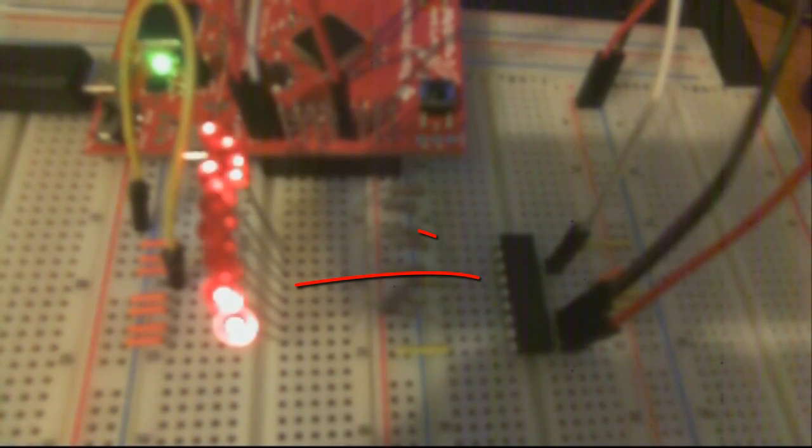In this tutorial, I want to show you how to use the SPI peripheral in your microcontroller to connect to an I/O expander. An I/O expander is an IC that basically lets you have access to more GPIO pins through either an SPI connection or an I2C connection. In this case, the I/O expander that I'm using uses the SPI communication protocol, and it lets you have access to 8 more GPIO pins through the SPI port on your microcontroller.